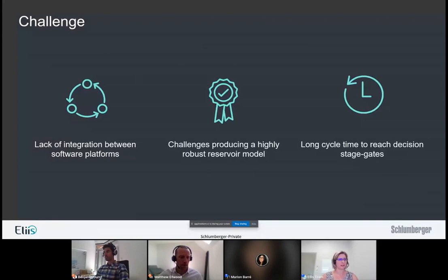Great, thank you, Matt. Another question for you. Are there options in the seismic stratigraphy process to extract horizons and review them separately before running a model update? Yeah, I think this is an important one because with complex models, the runtime and complexity in generating them can mean that it's very useful to QC the inputs before starting the process. So we did add an option to that utility to extract horizons and generate horizon interpretations in the input tree without updating the model. You can then review those and understand areas where maybe you have inconsistencies before updating